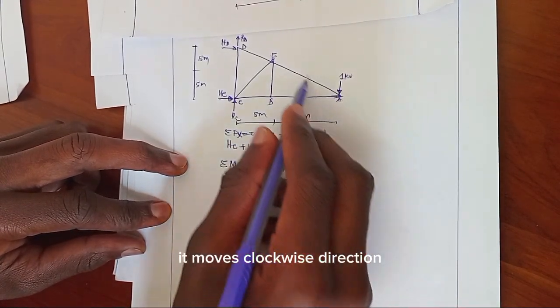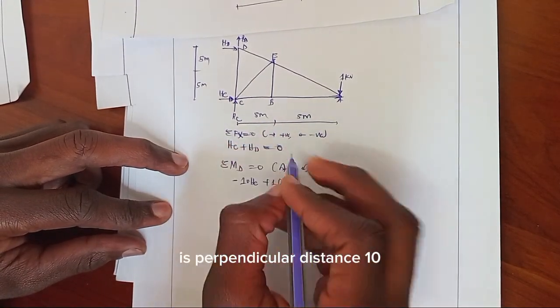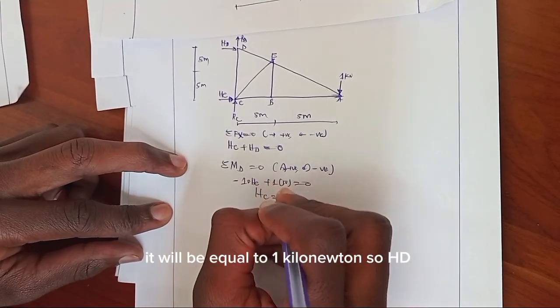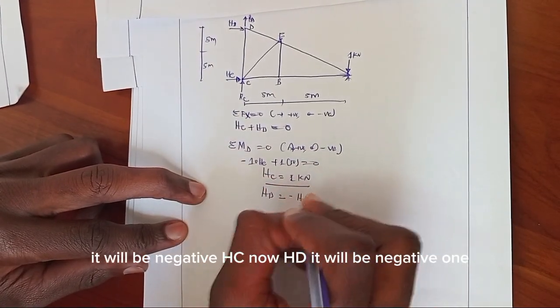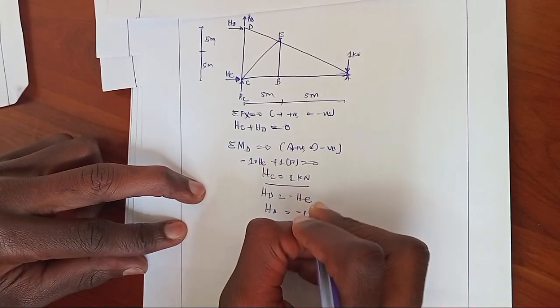This unit load moves clockwise, so it will be 1 times perpendicular distance 10. So negative 10 HC plus 1 times 10 is equal to 0. So HC will be equal to 1 kilonewton. HD will be negative HC, so HD will be negative 1 kilonewton.